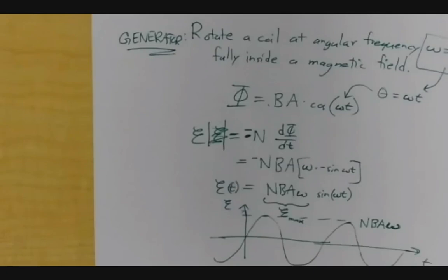And they're not the same, obviously. So you got a node rule at A and B, same spot. You have 4 node rules, and you do a bunch of stuff. How many equations did you get here overall? Yeah. And how many currents do you have? 5. You have 5. So you need one more equation.